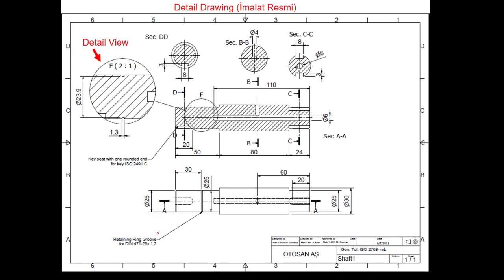Example for the shaft. Yes, this is a detailed drawing. In our example, it is the detailed drawing sheet for the shaft. Yes, at the title block, there is no part list, by the way. There is no balloon. Okay, this is the title block: name of the company, name of the object, tolerance note, quadrant symbol, and the name of the designer, etc. Scale factor.